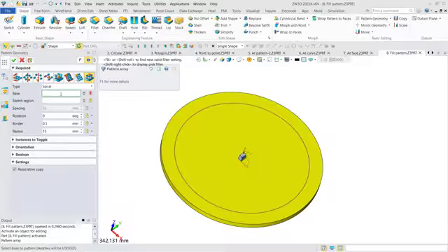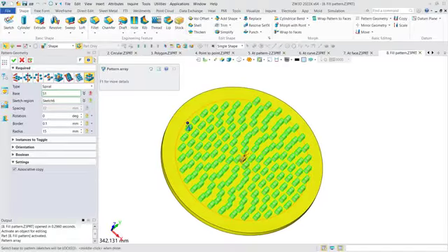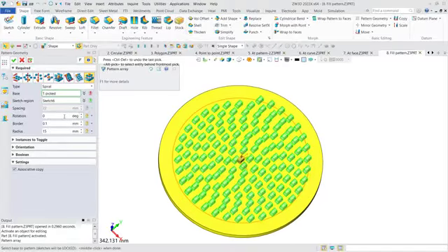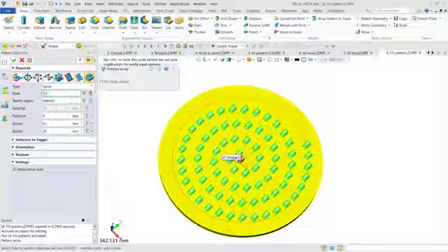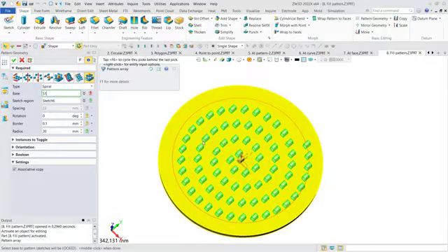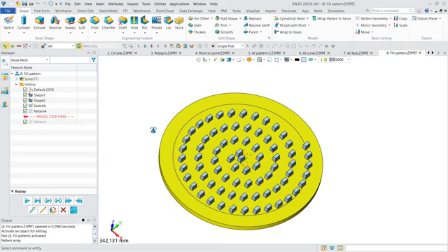Okay, first we define the base, and then we define the sketch region, and then you can see the preview. Here we can change the radius bigger, like 30. Okay, now you can see it's a spiral shape, right? From inside to outside. Okay. That's about the fill pattern.